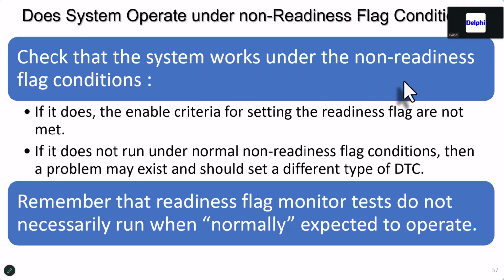Does it work under normal conditions? What I mean by that is, let's say the typical EGR, you have to meet certain criteria, warm-up criteria, speed criteria, load criteria to get it to operate. You're accelerating the car, you look at your scan tool and it says EGR is commanded on. Okay, that's non-readiness. We're not really testing it at that time for readiness. So you drive it, and you notice you can't get it, and we'll end with a case study on this to show you that. You can't get it to go, but at least you know it works. So what you're missing is the enable criteria to finish it off to check for performance.